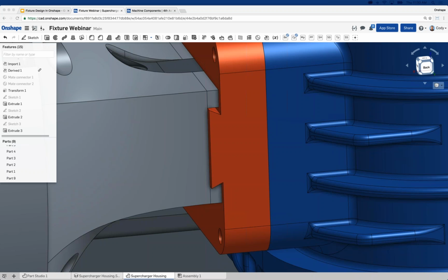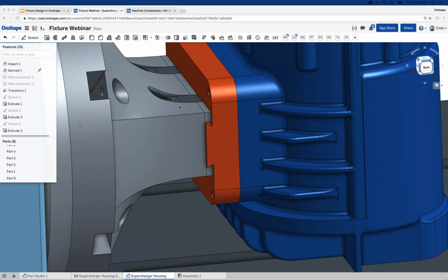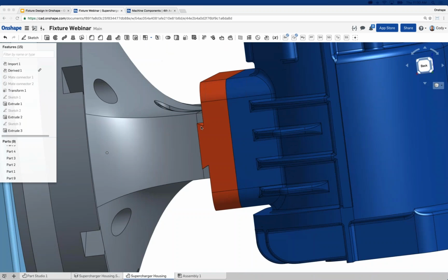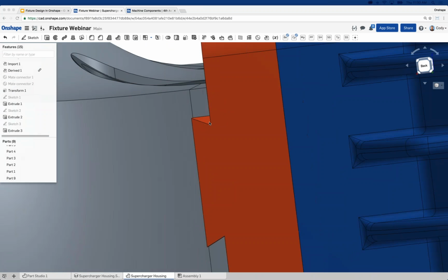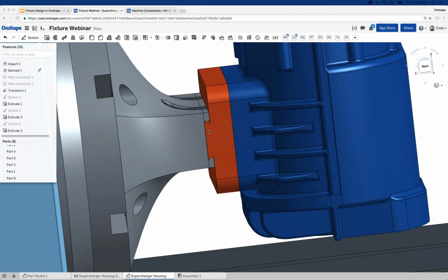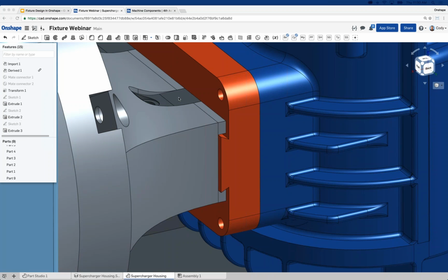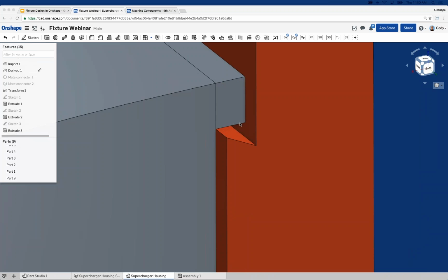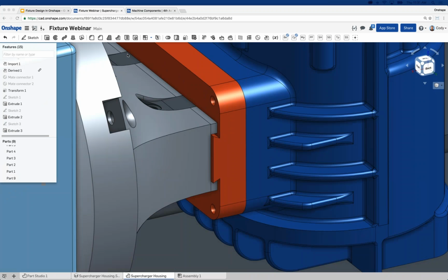This will not fit together. It is no clearance. Both parts have the same measurement in and out. That is not true. These will fit because these arms move up and down, right? So just keep in mind that these two clamp arms are what are actually attaching our dovetail, not this edge, right? So these two clamp arms move up and down, and that's what gives us our clamping behavior.